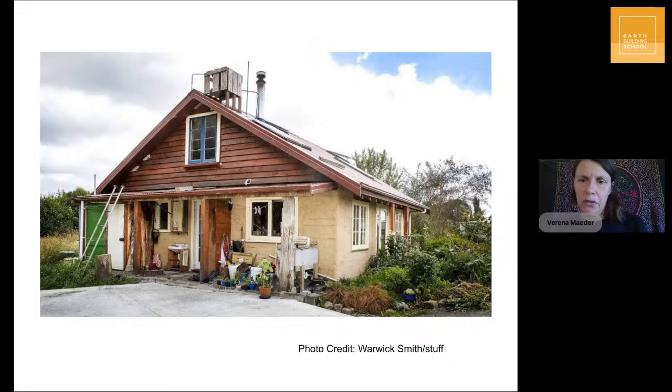Any specifics for green living roofs? There's a question that has come in. The only thing I'm saying is that when you're designing green roofs, you have to follow the whole way it is built up, the layers and everything. That's a whole story in itself. But as it relates to earthen buildings, with a living roof you're dealing with a heavy roof construction, so you have to allow for the weight.